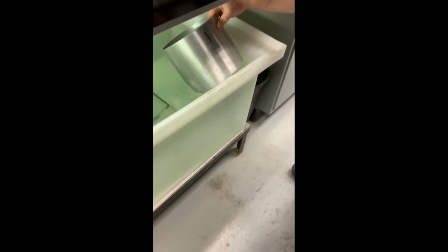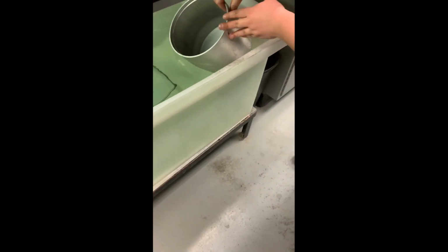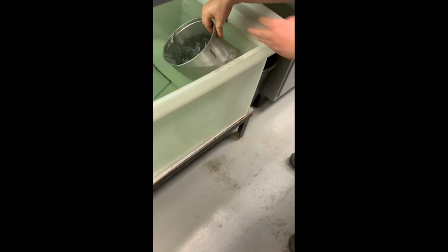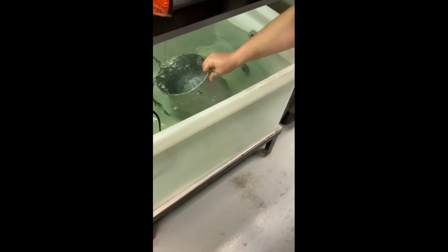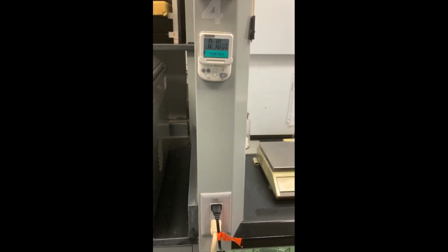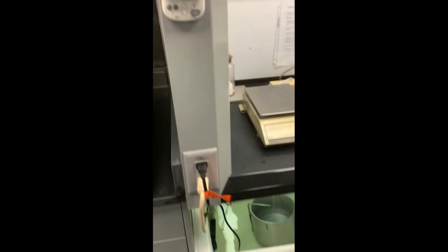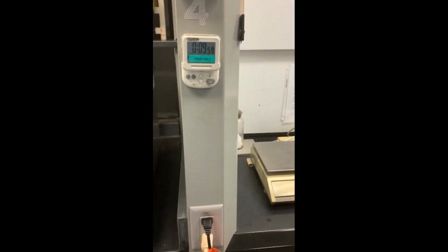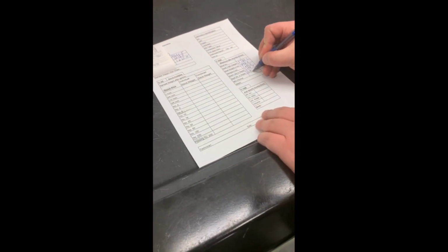After the sample is removed from the container, return the empty container to the water bath to get the empty weight in water. Using those weights, we can calculate the density without air voids.